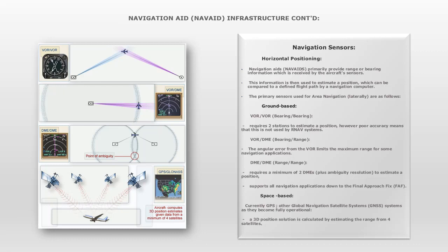DME, range, requires a minimum of 2 DMEs, plus ambiguity resolution, to estimate a position, supports all navigation applications down to the final approach fix.